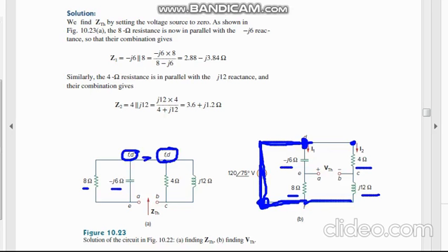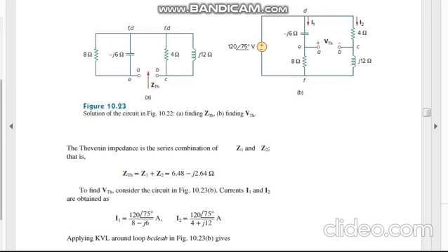So looking at the Thevenin impedance, you can just add up the two other Z Thevenins to find Z1 plus Z2, with these two parallel ports Z1 and Z2. Then you can merge this so that they are in series, and you can find out the Z Thevenin.